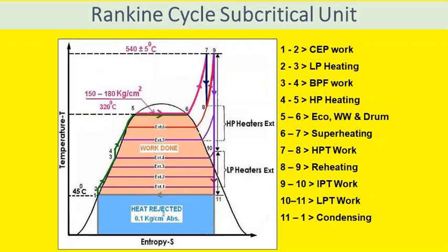There is a slight change in temperature of the feed water due to this work, and at the discharge of the boiler feed pump, that feed water is passed through HP heaters, high pressure heaters. 4 to 5 represents the high pressure heating arrangement as a part of regenerative feed water heating, where bleed steam is taken from the HP turbine and MP turbine.